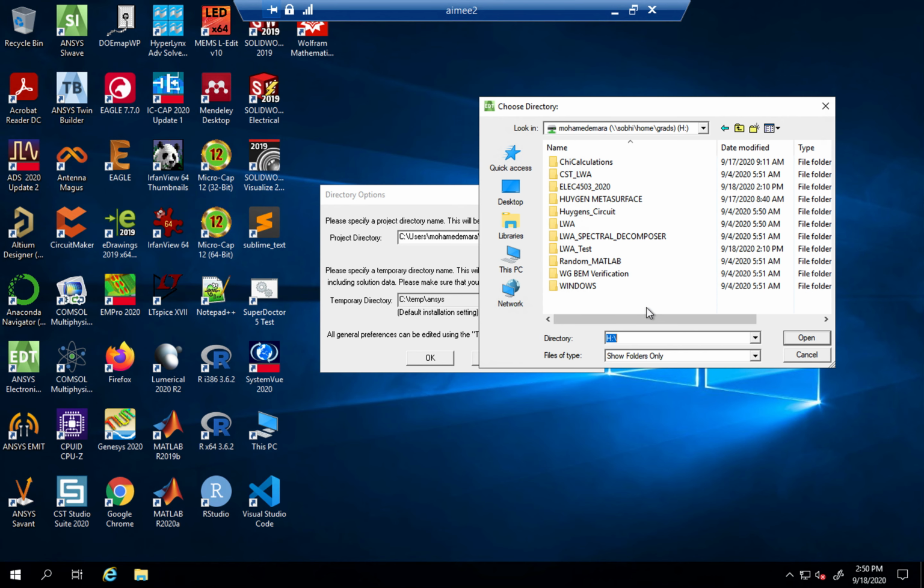So you can right-click and rename the project. So give it a meaningful name. So for us, we can call it the workshop. So lab 1. All right, so the project doesn't have any HFSS design yet, so that's what you need to add. So if you go under Desktop, you'll see that there's a bunch of software tools that ANSYS has, and the one that we're going to use is HFSS. If you go under HFSS, you click on the arrow, you can insert a new, yes?